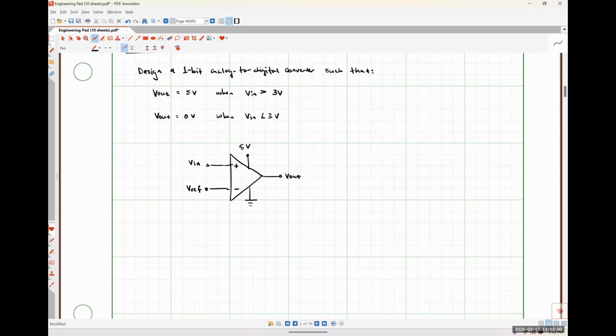So not a transformer. Well, this is DC, so a transformer wouldn't even work. What did you say? So we're not going to use a single resistor, but we are going to use a resistive divider, more commonly known as a voltage divider network, in order to facilitate this. So I might expand this guy a little bit. Those are still going to be at 5 volts and ground. But what I'm going to do is essentially give myself access to a 5-volt supply rail and a 0-volt supply rail, or to put it more bluntly, just a common ground rail down here.